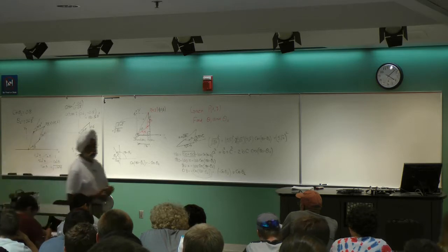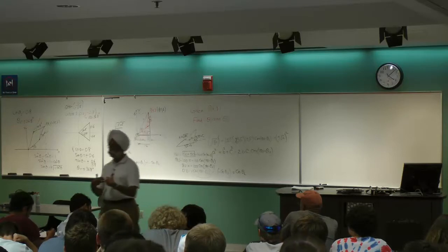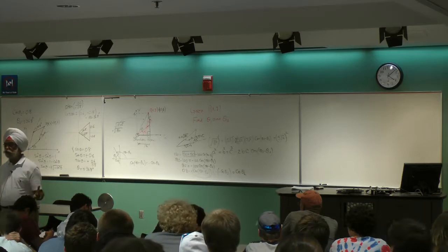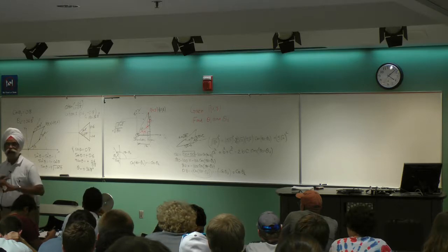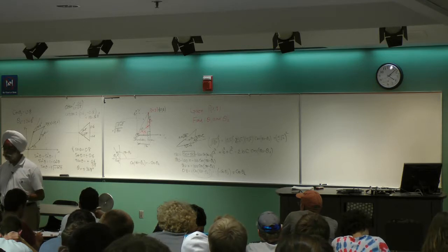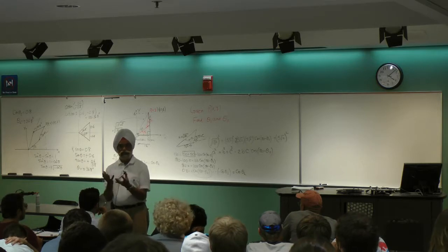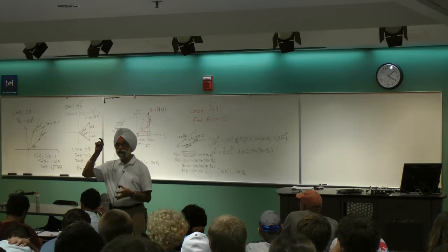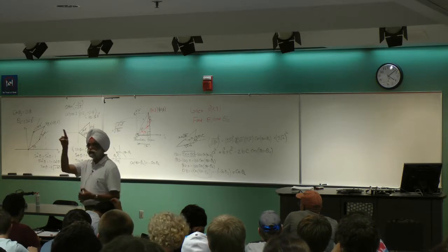Again, we'll talk more about that later on. I just got distracted because to me it's very important: I teach robotics, and we get the wrong answer if we don't do that. So you always use atan2. It will give you the right answer regardless. It's called the four-quadrant arctangent, whereas atan is known as the two-quadrant. It's only good if cosine is positive. If cosine is negative, it will give you the wrong answer, if you are in the second or third quadrant.